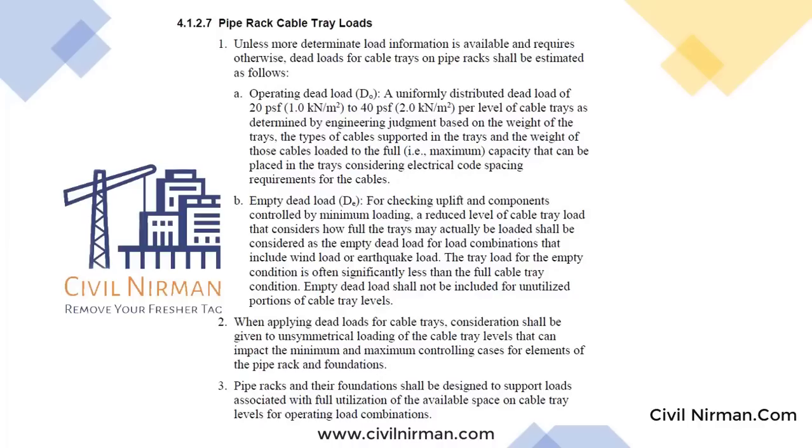When cables are running horizontally along the length of a pipe rack, supporting beams are generally needed every 6 meters, and at the turning, support is provided every 3 meters. While cable trays are running vertically along the height, every 3 meters a support is needed. At the end where cable trays are ending, the allowable cantilever for a cable tray is 1.5 meter. Beyond that, it is not permitted to extend without any intermediate supports.